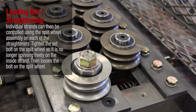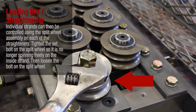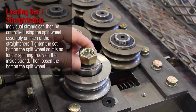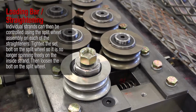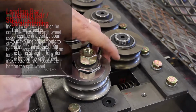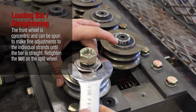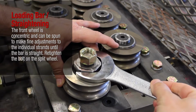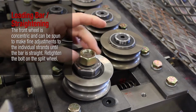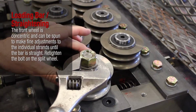Individual strands can then be controlled using the split wheel assembly on each of the straighteners. Tighten the set bolt on the split wheel so it is no longer spinning freely on the inside strand. Then loosen the bolt on the split wheel. The front wheel is concentric and can be spun to make fine adjustments to the individual strands until the bar is straight. Retighten the bolt on the split wheel.